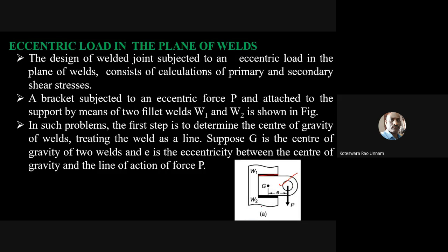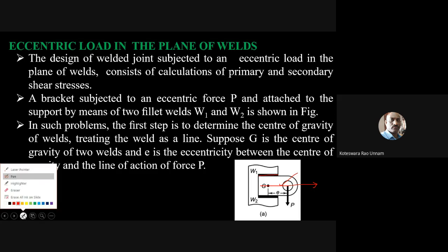We'll simply call it a fillet weld. We call it a parallel fillet weld if the line of action of the force is parallel to the length of the weld, or else if it is perpendicular, we call it a transverse fillet weld. Here they look like transverse fillet welds, even though the load is eccentric.